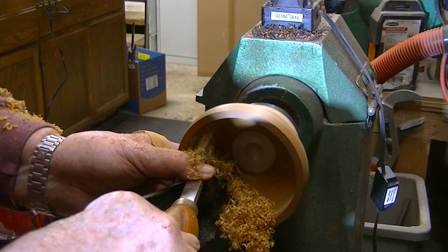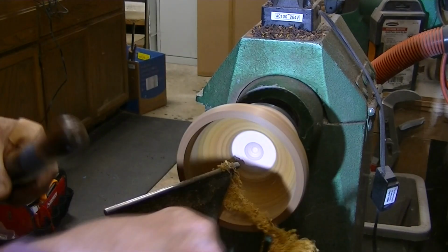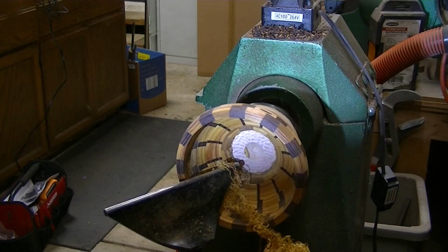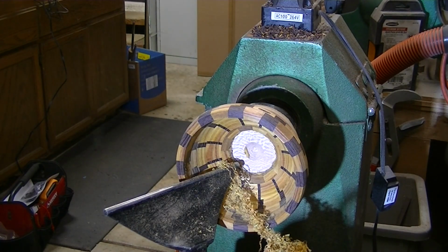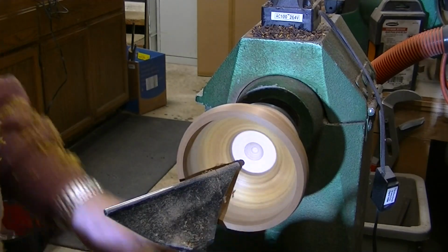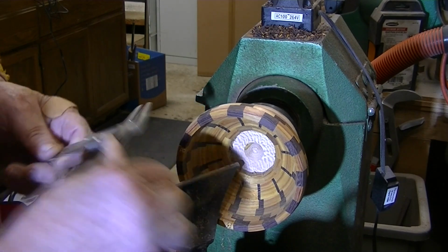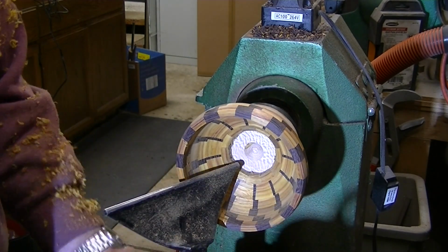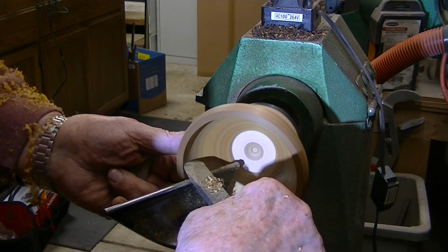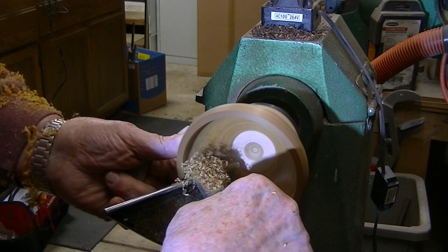Scrapers cut less aggressively on the pull than they do on the push, and so some of my final cuts on the inside of this thing are from the top where the glue block is to the center. I am checking the wall thickness of the base to be sure that the top will have the same thickness. So when the joint is connected, the inside edges will also match up as well as the outside. If they don't, I'll have to go in through the opening and fix that, and that's not something I prefer to do.